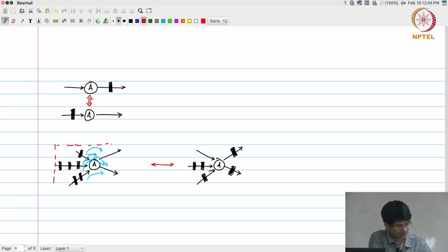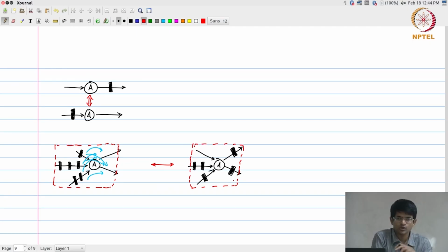Anybody who is outside of this box that I draw over here cannot tell the difference. Anybody who is observing it from outside this boundary cannot tell that there has been some movement of registers around the functional units inside. And that is actually quite a powerful claim, because effectively what it's telling you is you can now look at a part of a graph, do some retiming on it without having to worry about what the rest of the graph looked like. And the fact that you have made this isolated change over here can in turn impact the critical path through the entire circuit.